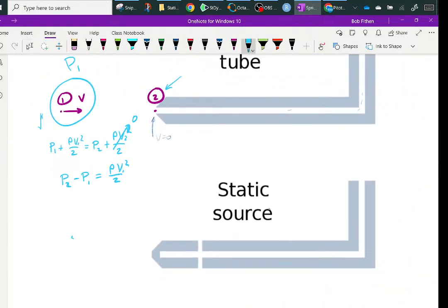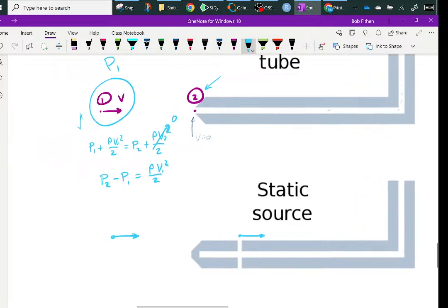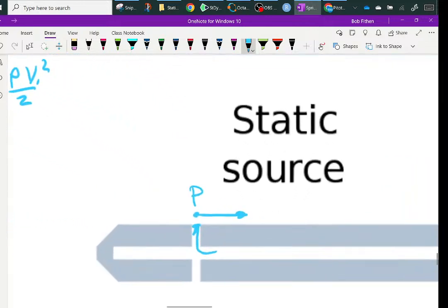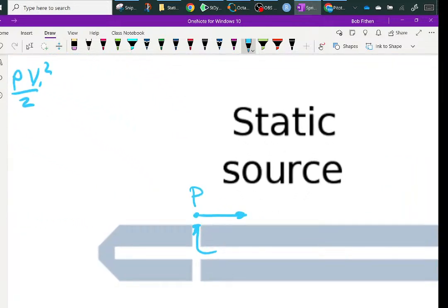So what you have here is you write between here and this point, and if the velocity is the same, this will pick up the static pressure, the pressure on the side. What you're going to get is the pressure here is the same as the pressure here. If this pressure becomes lower, it'll suck stuff out of here. If it becomes higher, it'll push back in there.